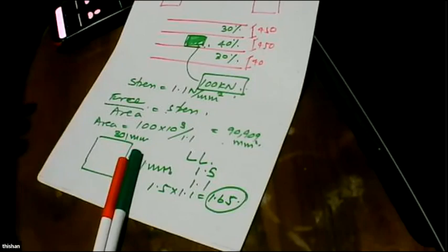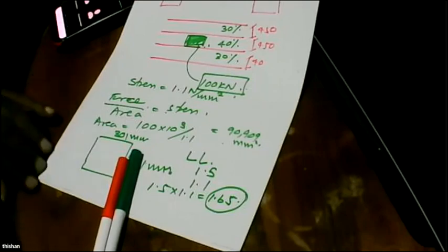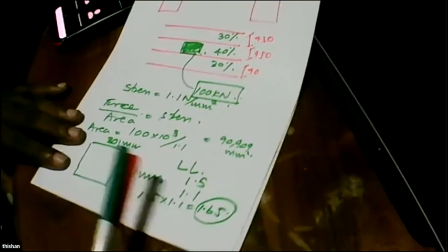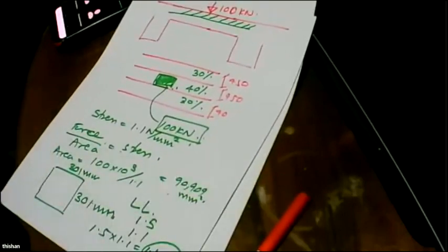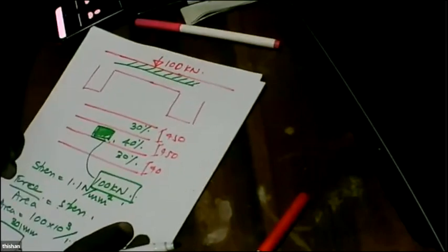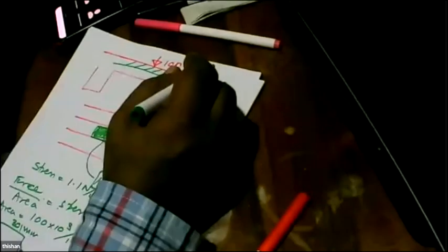So this way you can determine the reinforcement in the top slab, considering 2 different scenarios. First scenario is that it's subjected to the normal UDL, but the second scenario is it's subjected to a point load, right?